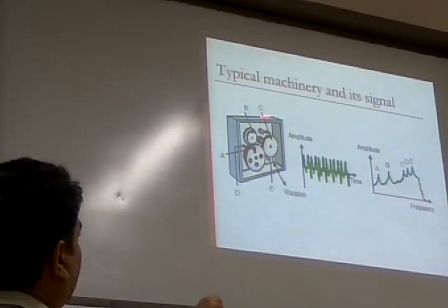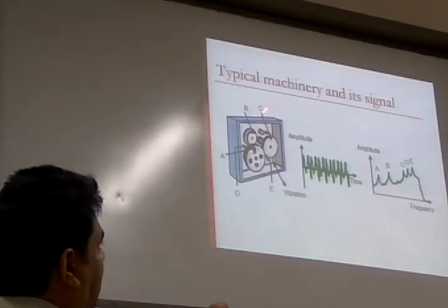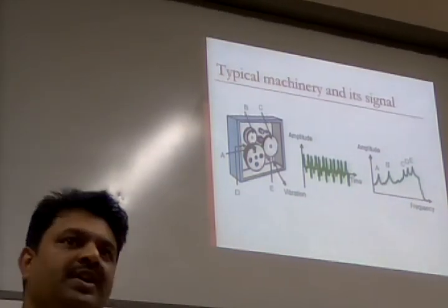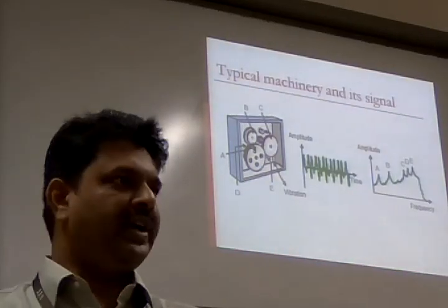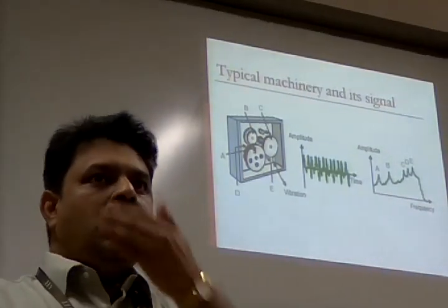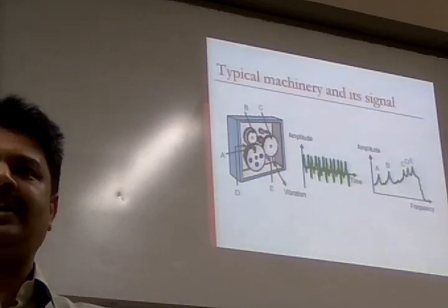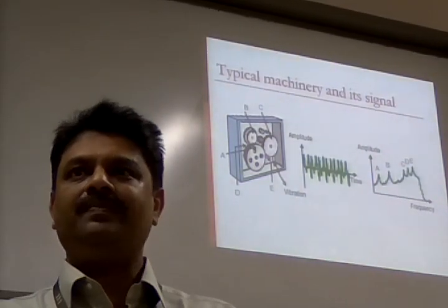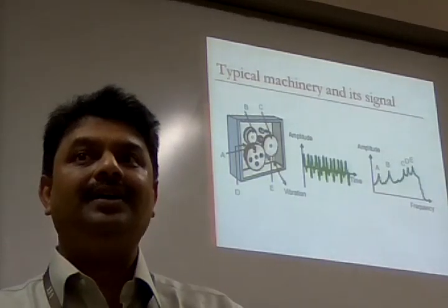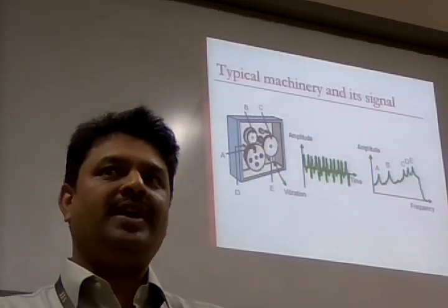You have a typical gearbox, put an accelerometer, take the time domain signal, do FFT. FFT, you have heard of it? Fast Fourier transform. You have heard of Fourier transforms? Yes? What is the role of Fourier transform? What variable to what variable?